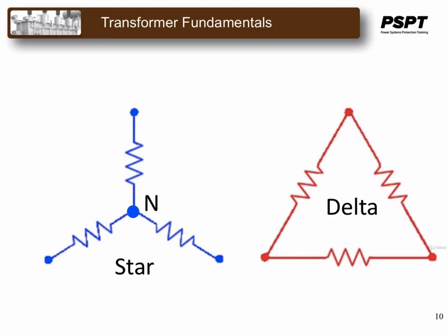Such a connection is used at some transformer stations to supply three-phase power to motors and single-phase power to, say, the lighting system. Delta circuits are mostly used for straight transformation of three-phase power of medium voltage range, where single-phase loads do not have to be provided for.